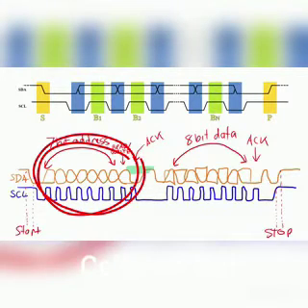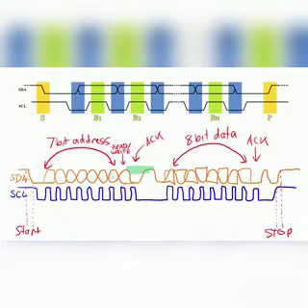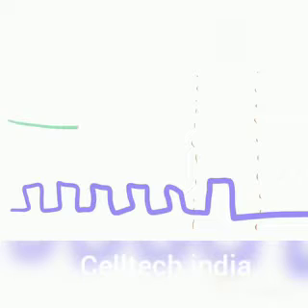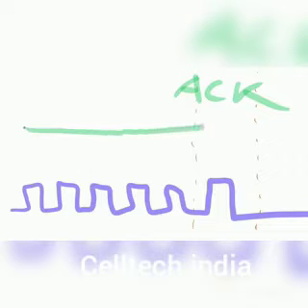The address is between 0 and 127, and this is a 7-bit address. There is another type of address, 10-bit addresses, but we're not going to talk about them here. If a device exists on the I2C bus with the address that was sent, then an acknowledgement will be received. That's when the line is pulled low. If there isn't a device with the address that was sent, then the acknowledge line will stay high.